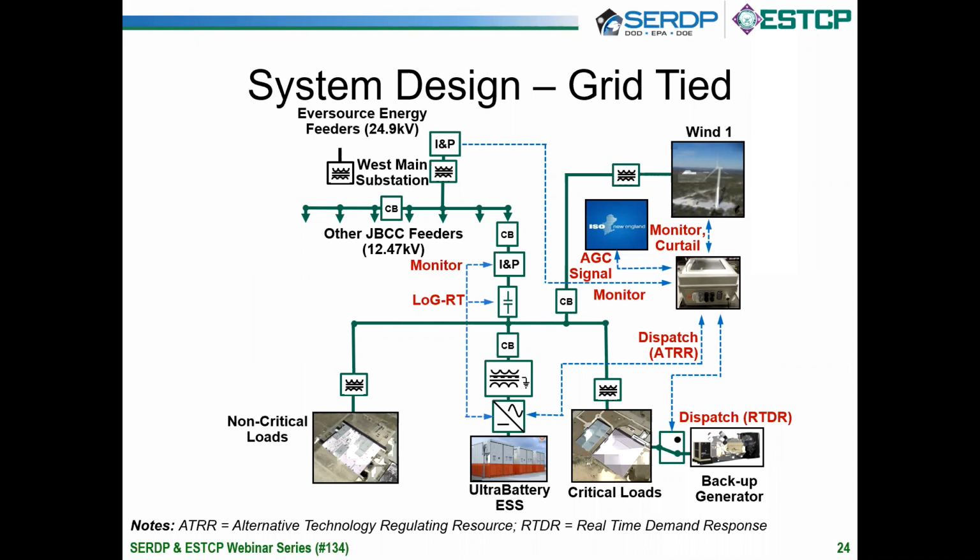So, coming back to the prior economic slide, we were able to demonstrate participation in frequency regulation, and demonstrate the ability to support real-time demand response. And the way that the base procured their power, they didn't have access to the capacity tag management, but the battery is now enrolled in essentially what amounts to a utility demand response program. So actively right now the base has outstanding contracts to do frequency regulation and utility demand response, and pending using the generator, our ISO demand response is pending for other reasons I'll get into later.